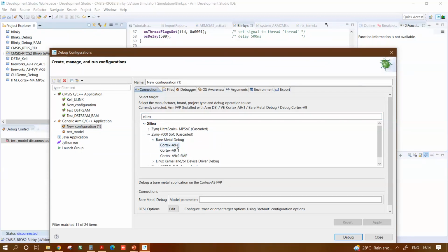So based on the processor you select, like if you go for the Freescale Hybrid series, it has a Cortex A5 and M4 combination. Like if I go for this one, this is also A5. Yeah, this one, Cortex A5 and M4 combination. This is the hybrid series. So the multi-core debugging option comes based on what processor device you have selected for your project. Based on that, you choose which specific processor core you want to download the code to and test or debug the code. Okay.